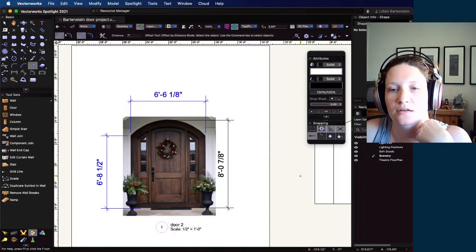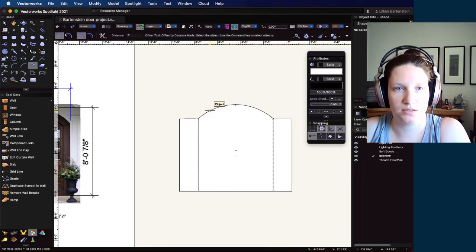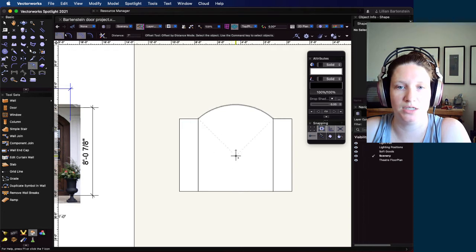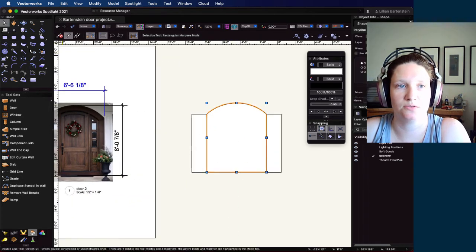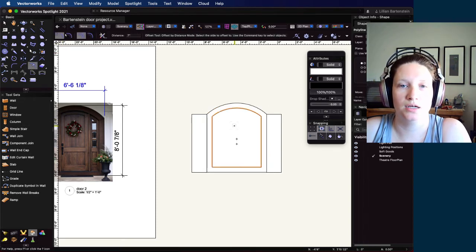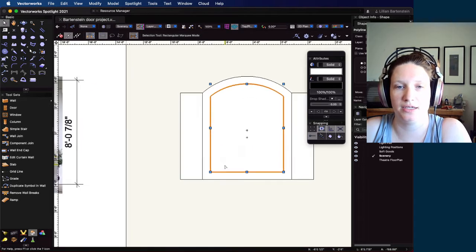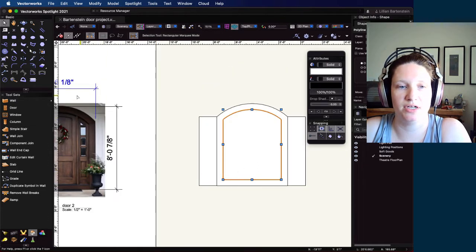And then we hold down Command. Is that right? Yeah, we hold down Command or Control on a PC. Maybe, maybe not. Let's select it before we pick up the offset tool and see if it's happier with me. There we go. And it now has created this shape inside. That's great. I like it. Okay. So that now has given me that 7-inch border all the way around inside. So that covers me for all of this stuff, right?